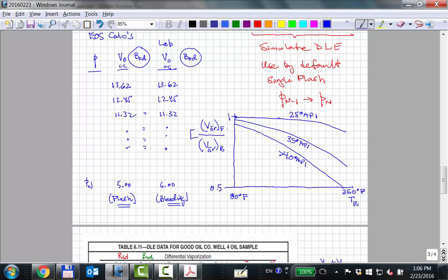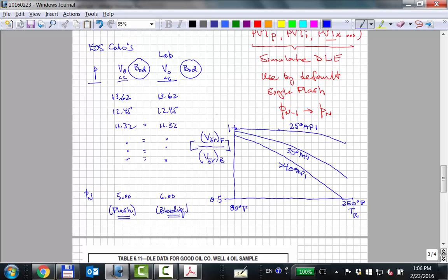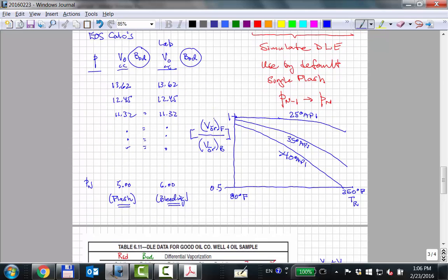Basically, if this ratio is less than about 0.97, that's 3% error, you should be concerned as a good engineer. Concern meaning you go back and retweak. You go back and try to do something to avoid this problem. Different programs allow you to handle this in different ways, but by default, if you just put the numbers in, you're going to get a problem.